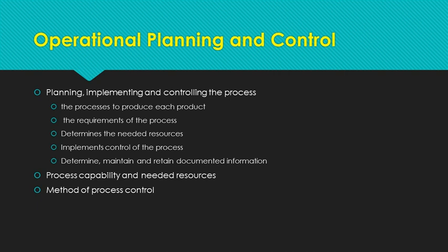This is the answer as to why companies charged with designing the manufacturing process for a product controlled by the customer are not design responsible. This is the point where the company must understand the capability of their process and equipment and determine if they are capable of producing product at the parts per million defect level and any other requirements of the process such as temperature, pressure, etc.